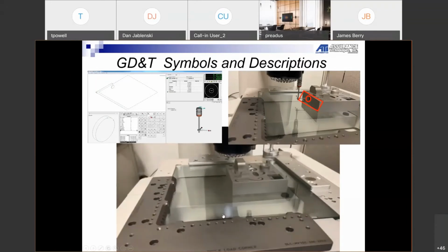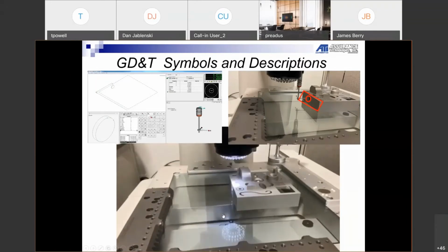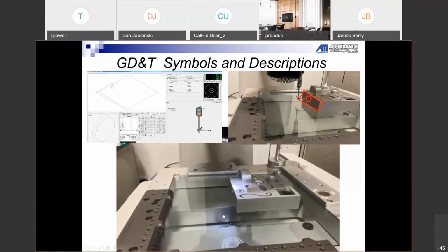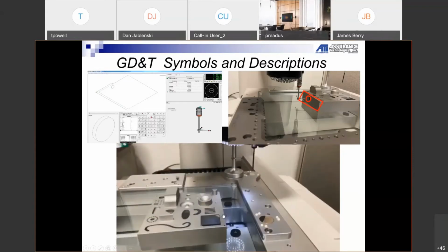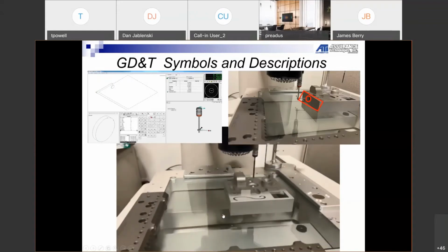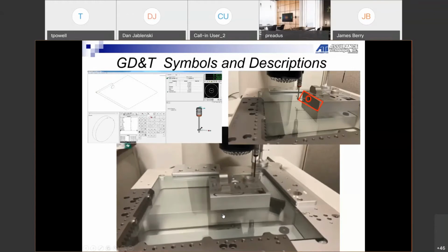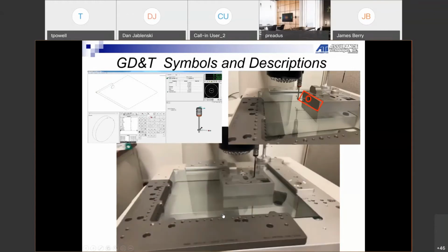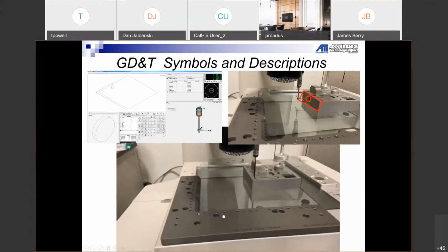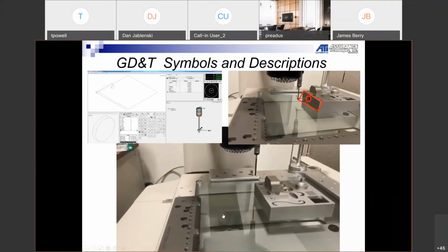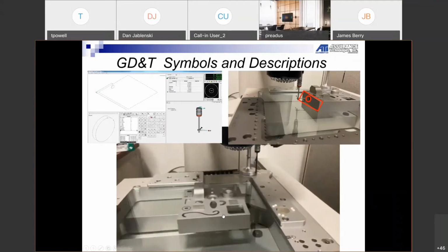The first thing I did was I measured with the camera, and vision is measuring the top plane for some of the other features. And then I'm able to go grab a straight probe and come measure the top plane for some other features. So when you're programming, especially with touch probe, we talked about, I believe in one of the earlier webinars, battle planning when you're programming a part.